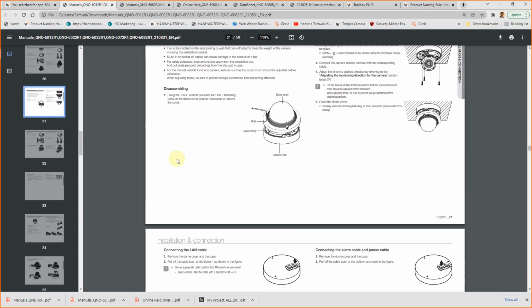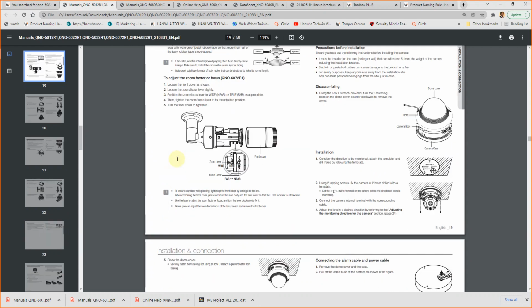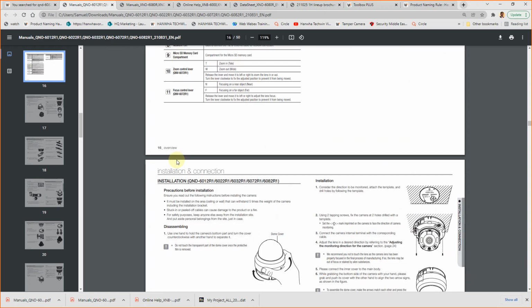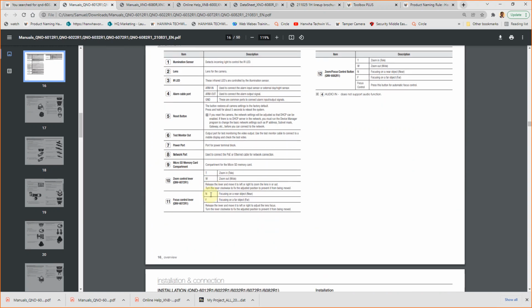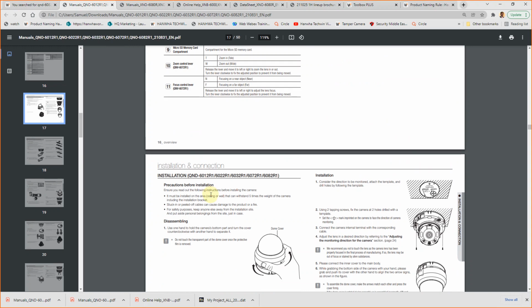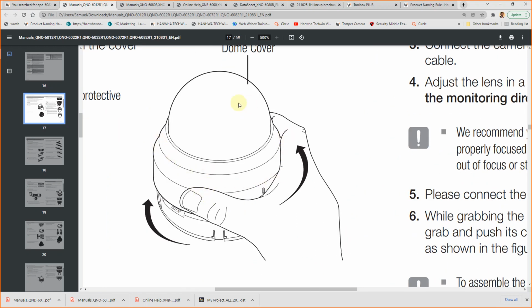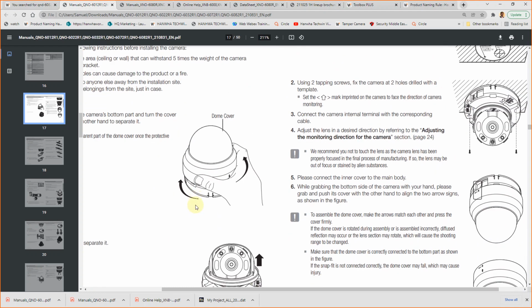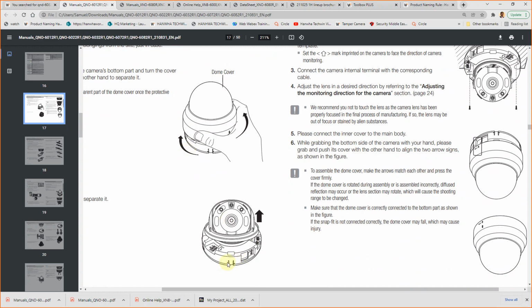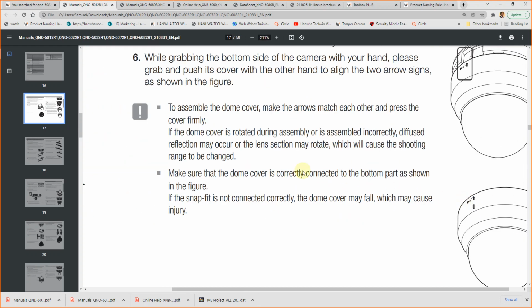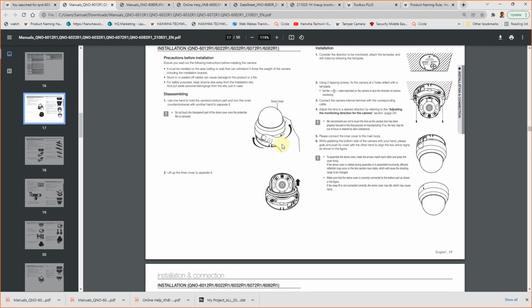Next then comes your dome camera. Again, the same. This is an indoor dome camera. There are no screws. So how do you open? You see the lock button? Oh, it's not visible. You will find here a lock unlock marking. You just have to twist the knob. You can see here, you just have to twist the camera front cover and it will unlock.